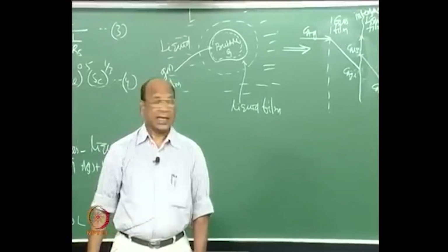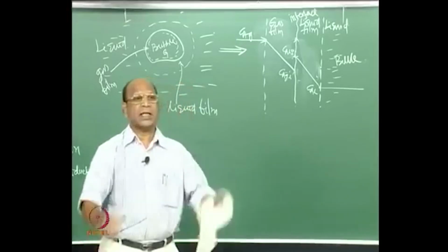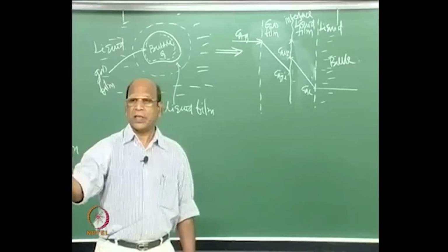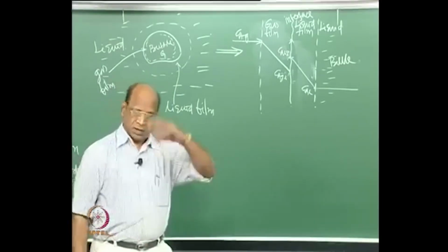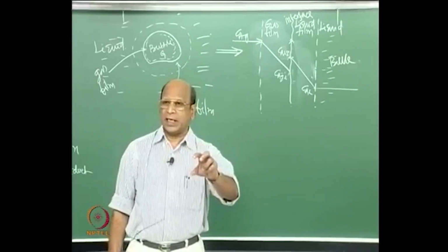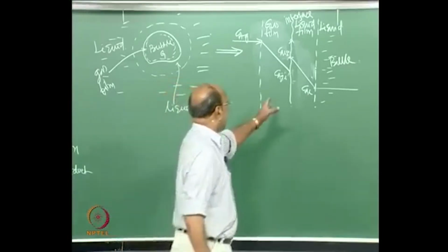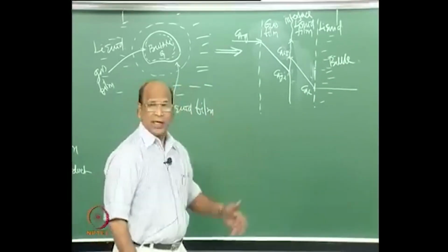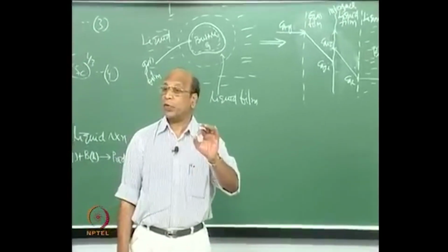And if it is further very slow, then where is the reaction taking place? In the entire bulk. At that time, your batch equations are directly useful. It is a heterogeneous system, but the presence of gas will only occupy some volume, and it is not really reflected in the rate of reaction, because the rate of reaction is so slow. Then the reaction takes place through the entire liquid. So you need normal batch reactor design expressions for that condition where you have a very slow reaction.